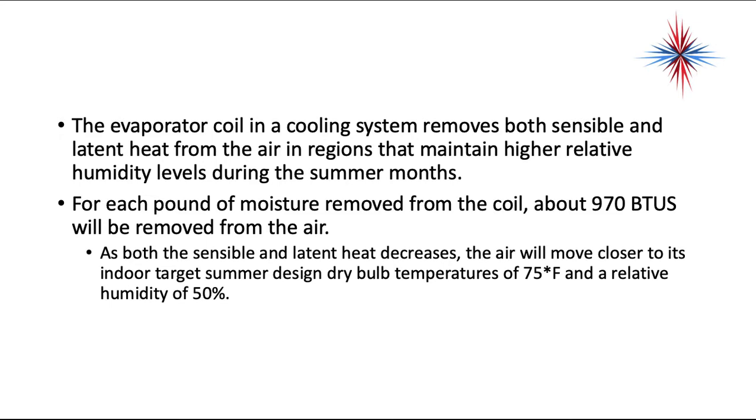As both the sensible and latent heat decrease, the air will move closer to its indoor target design dry bulb temperature of about 75 degrees and a relative humidity of 50%. Remember, anything over 50% relative humidity, we take a chance in growing mold. So we want to maintain our relative humidity in indoor environments under 50%.